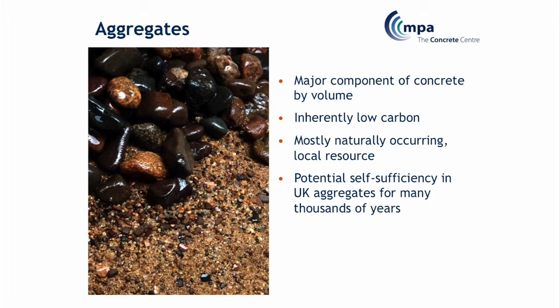Now aggregates, as we said, is by far the largest proportion of the components of concrete. It's inherently low in carbon, and actually in the UK we're blessed with having potentially thousands of years of supply. It's very plentiful, naturally occurring, and it's local, which is an important sustainability credential. Through BREEAM and various other considerations, recyclability and using recycled content has come to the fore. And one of the questions that we get asked quite a lot is how much recycled content can we use in concrete, and where do we get hold of it?